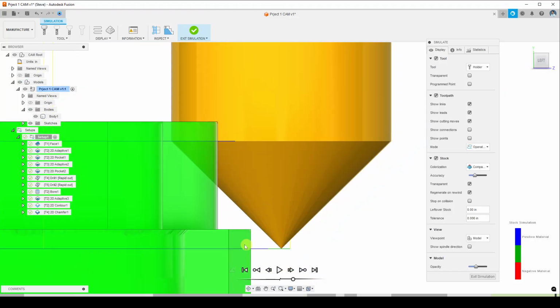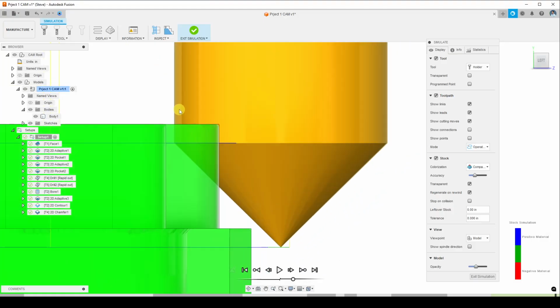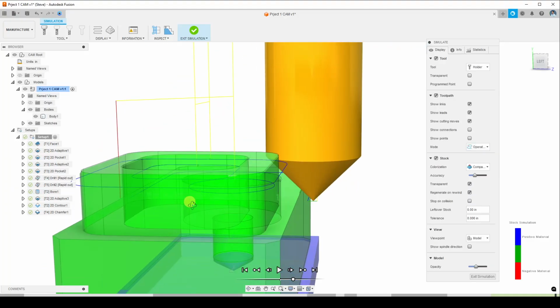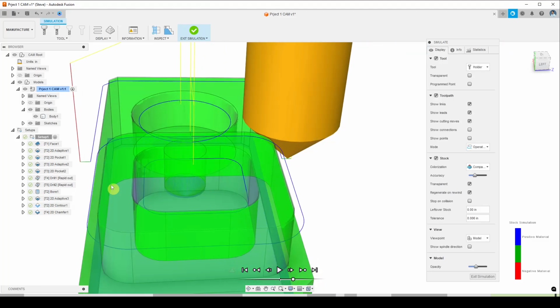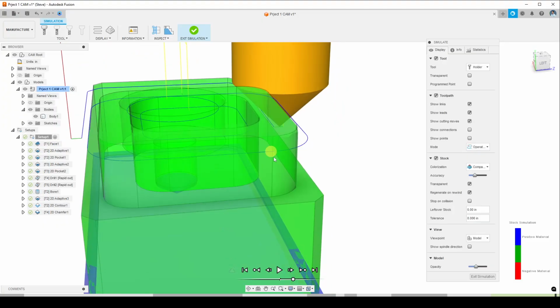So how do we get a chamfer on that? There is a way, and I think the way is going to be increasing the chamfer tip offset, but just for that. So have the tip stick way down here. It's going to move the edge of the tool over as well. It'll only work for this bottom one, because if you were to try to do it up here, the tool might be too big, or you might get some collisions with different parts of the part.